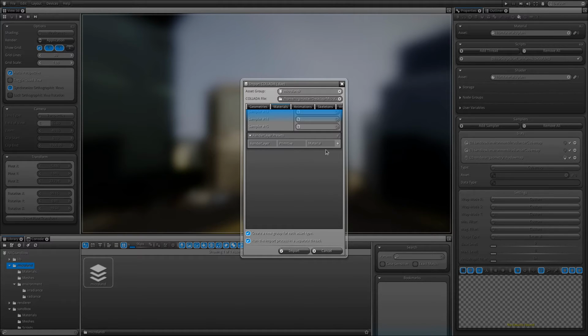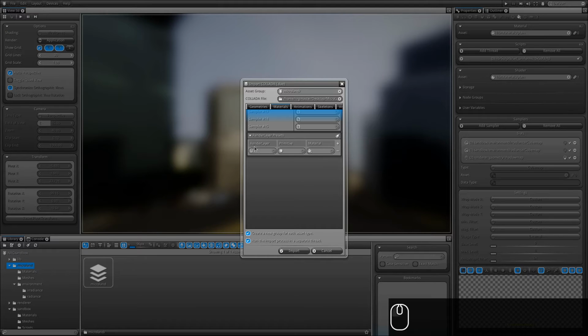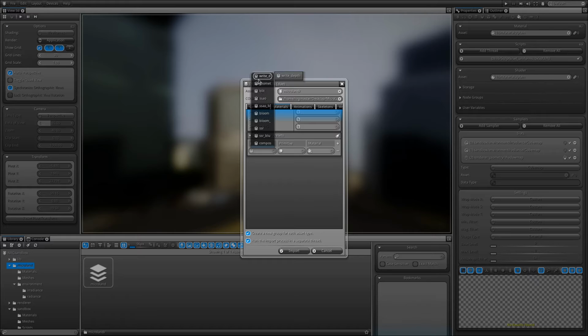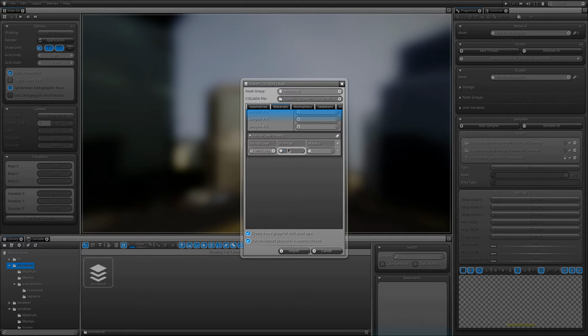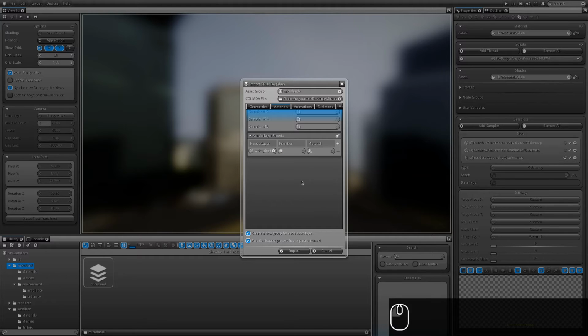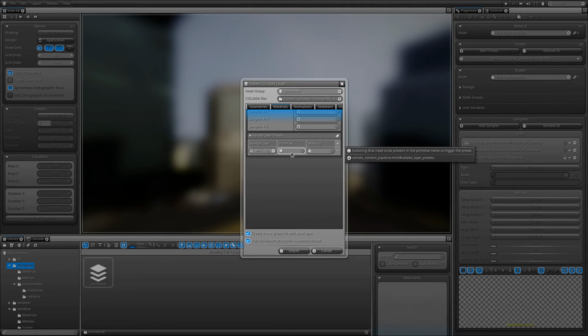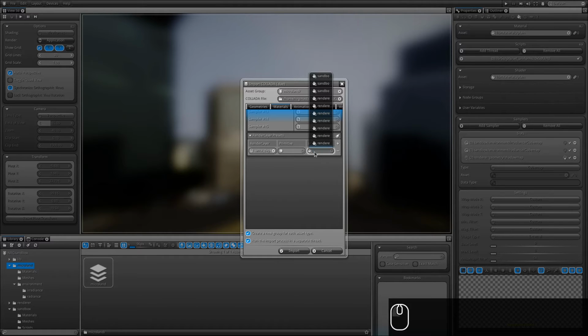By creating a rule like this, I'm going to be able to say that each new object that is going to be placed on right depth has a specific identifier in the primitive name. By leaving that empty, it means all primitives that are part of the geometry. So this is exactly what I want to do. Every primitive part of that geometry that is placed on the render layer right depth, I am going to apply the right depth material.